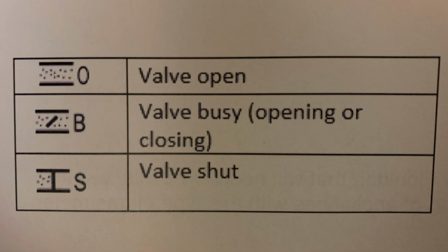Now this meter displays a symbol in the top left hand corner of the display that indicates the position of this gas valve. So before you commence with the gas rating, the valve must be in the open position. If the valve is in closed position, then the customer will either need to put credit onto the meter or you'll need to contact their gas supplier for further guidance.